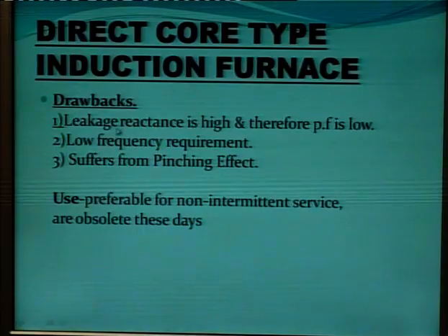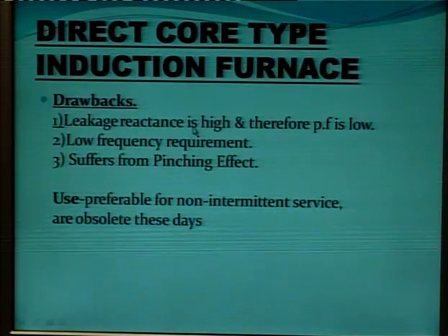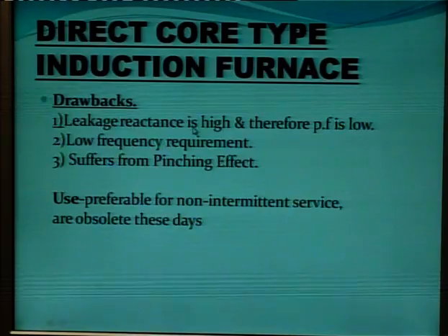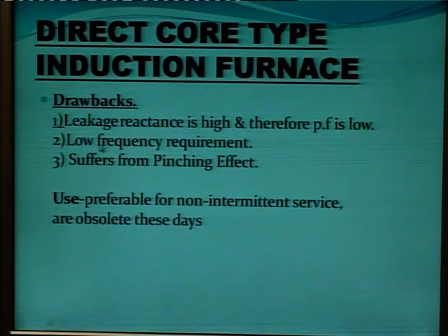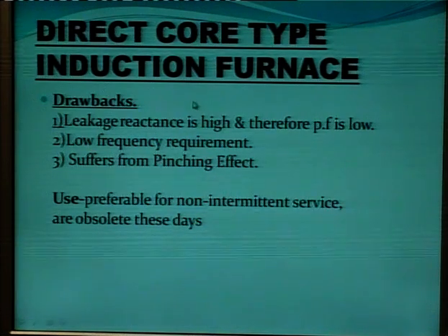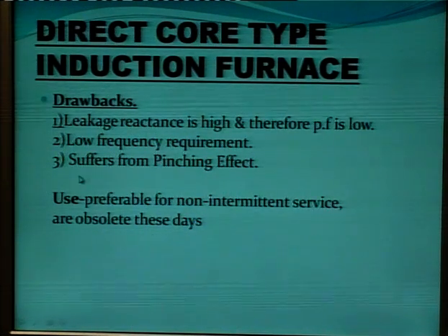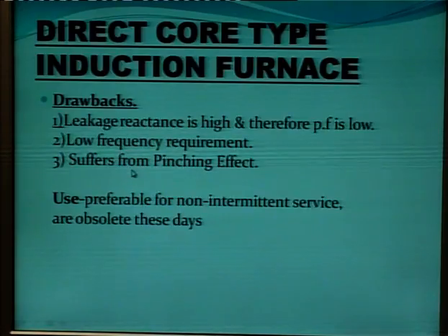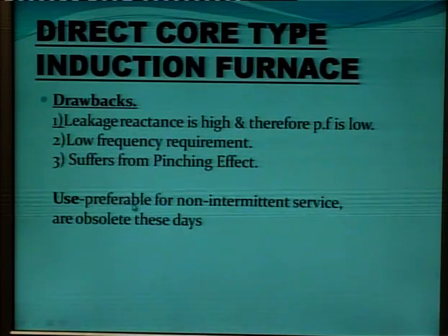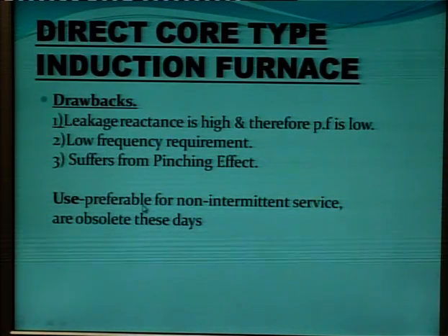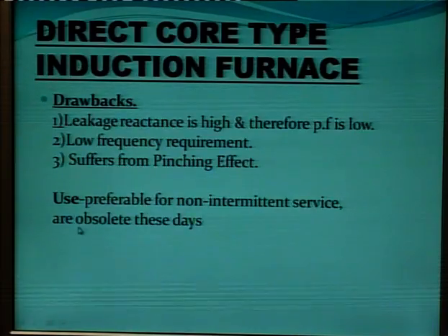So drawback is leakage reactance is high, therefore the power factor is very low. The second is low frequency requirement. So extra generator set is required, and it suffers from the pinching effect, and it is preferably used for non-intermittent service.